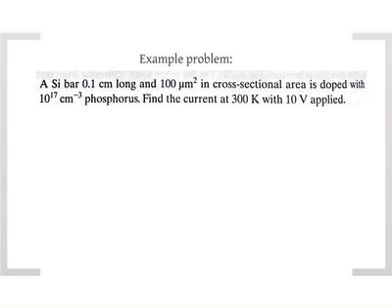When you apply Ohm's law, voltage is given. You need to know the resistance. Resistance is related to the geometry of the material through conductivity and resistivity. And all you need to do is calculate conductivity, or resistance. It's the same, they're reciprocal. And of course, conductivity is related to mobility and carrier concentration. This is what we have been focusing on for the last two classes.